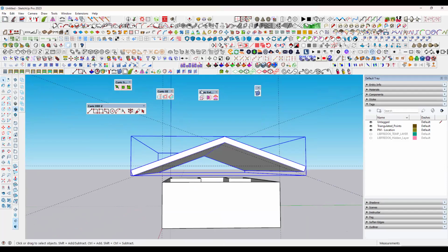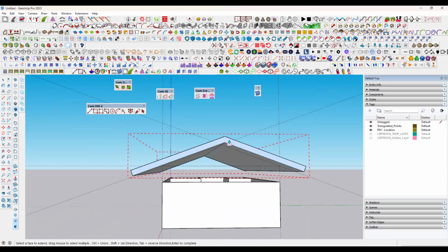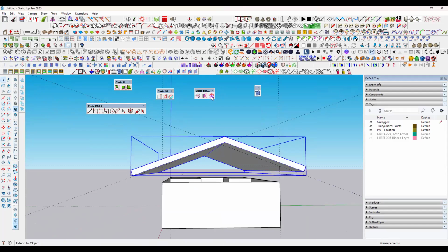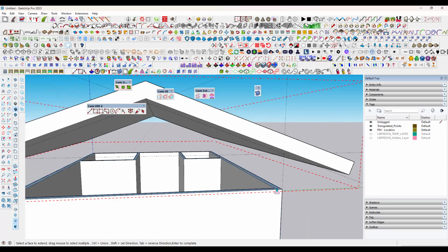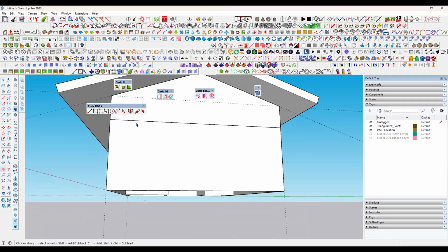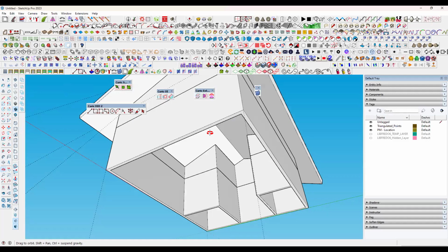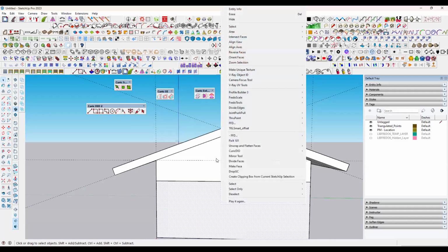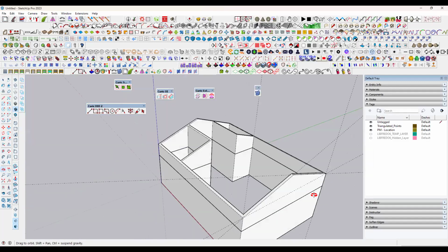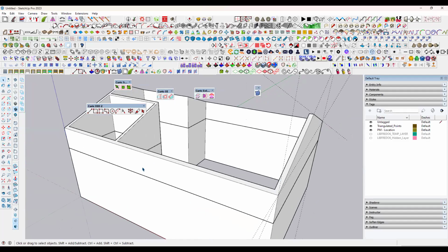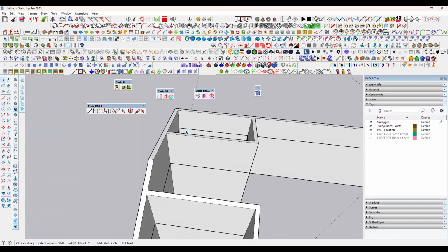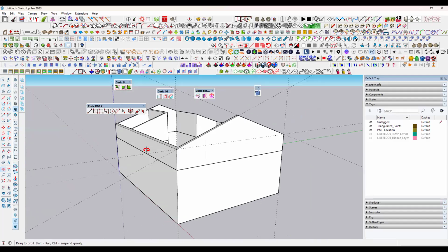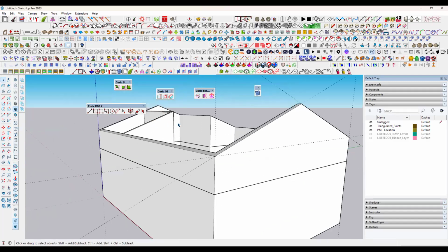In the same toolbar, we have one extra tool, this is the extend. I'm going to click this component, select this component, then select this space. Whenever you select this space, see automatically it is created and it aligns to the surface automatically. Now when I hide this one, see everywhere, whenever you have surfaces, even in the internal walls and exterior walls, everything is going to be touched, even if it is an inclined roof.